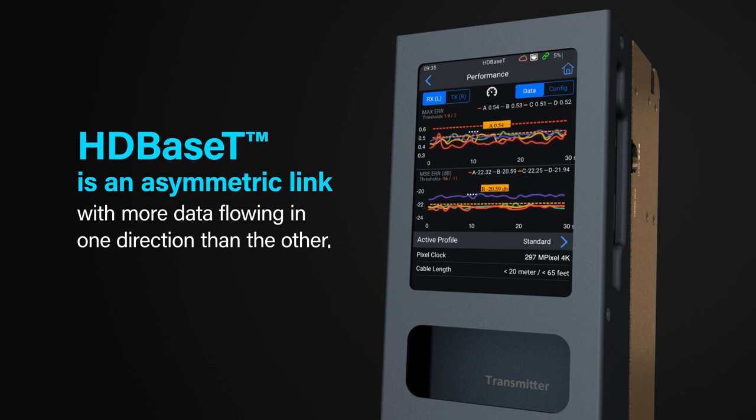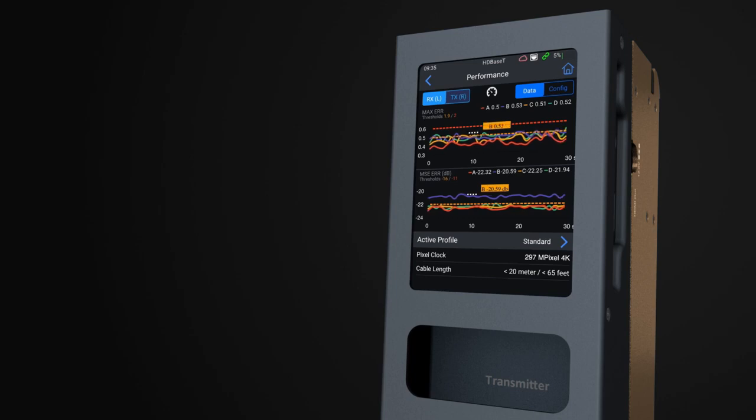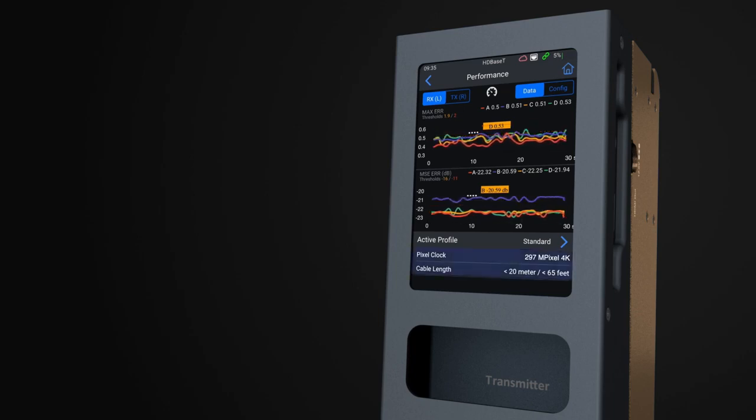The MS Test Pro can test the data flow in both directions by toggling the TX or RX switch at the top of the screen. Supporting data is recorded at the bottom of the tester screen, including the cable's length and the pixel clock speed of the HDMI signal being sent.